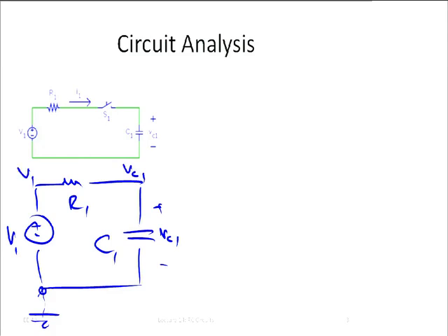So we have currents, again, IA, and we have current IB, and the sum of these must be 0. Hey, we did that many times, right? Okay, so, well, IA, that's fairly easy. What is that? VC1. And now, that's another thing that I often do. I show that VC1 is actually a function of time, right? It's going to change this time. VC1 of t minus V1 over R1. Okay, so that was easy.